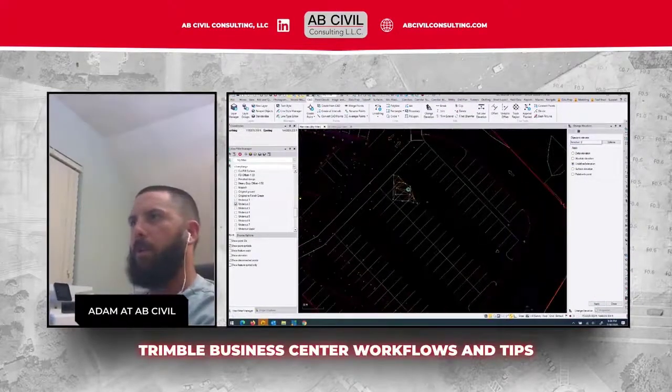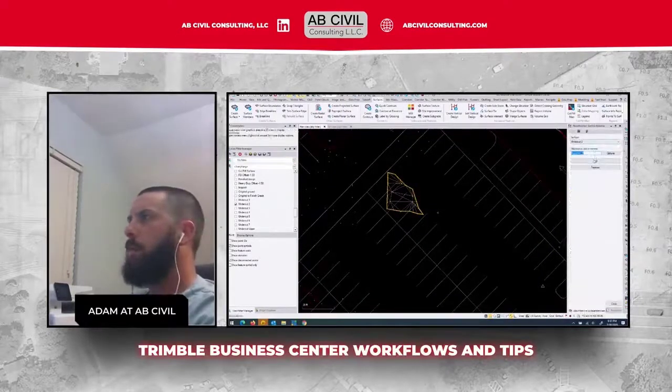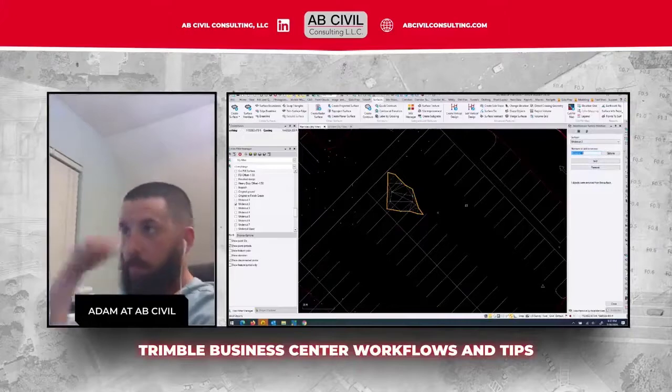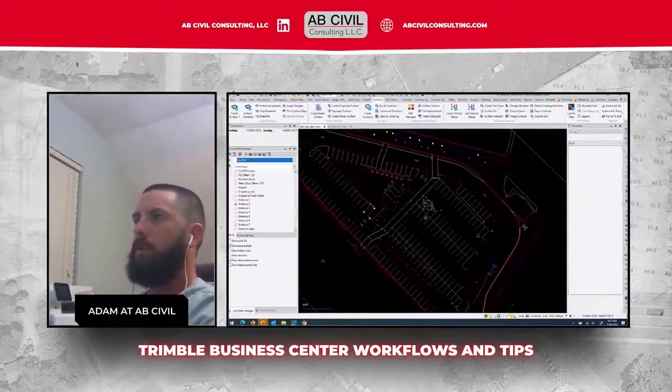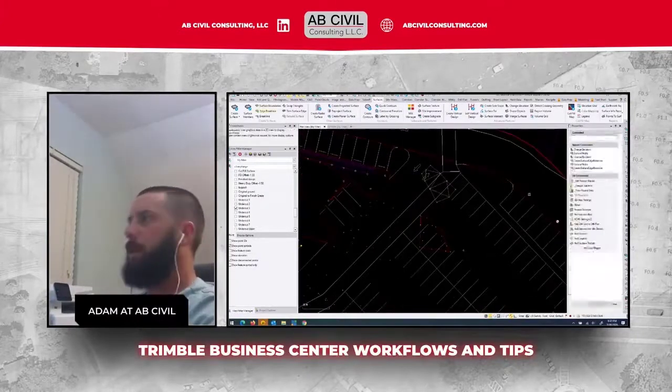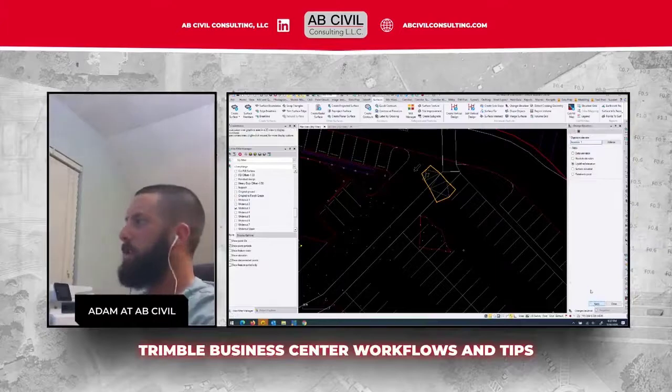So try to follow. I'm just going to do this with all 3. So edge break line, remove it from Undercut 2, Control D for me, undefined elevation. I'm going to turn on surface 3, edge break line, remove from surface, make it undefined so there's no elevations tied to it.